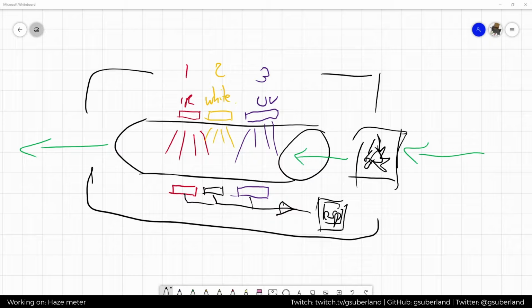And the UV light sensor has 16-bit resolution, which is pretty good. The resolution is good, and I will probably get some pretty good resolution on the UV side, and on the IR side as well, just by using a decent ADC. I can't remember what resolution the built-in one is for the ESP8266. I think it's 12-bit.